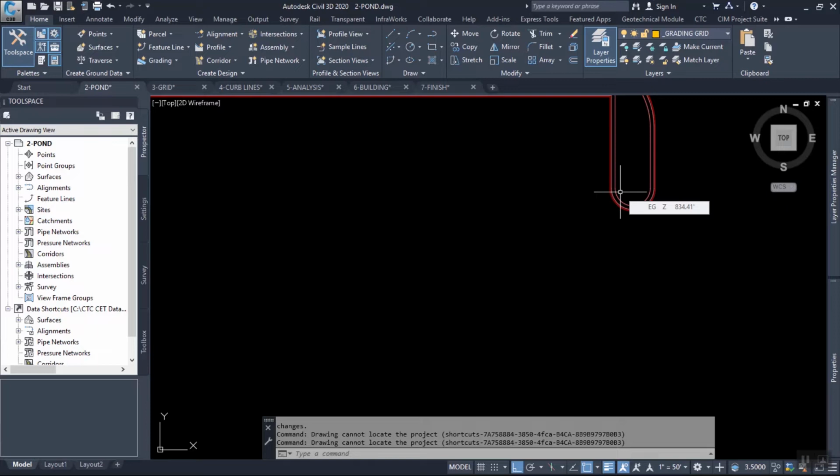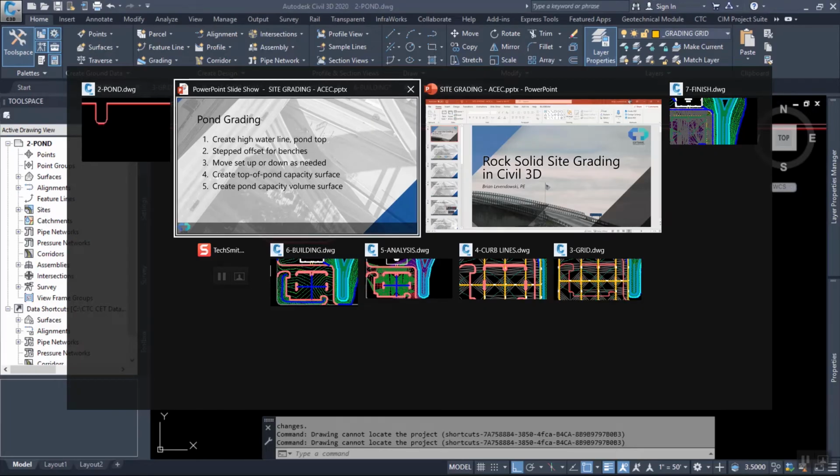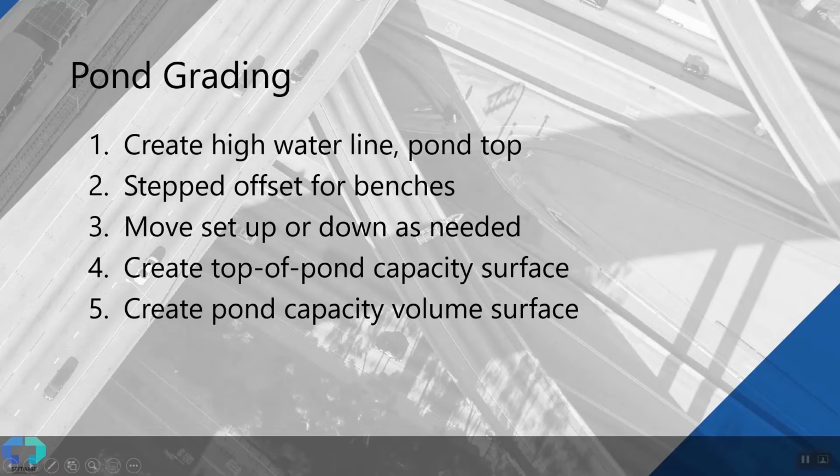Okay, if my whole parking lot sheet drains one way, it's great. So what I'm going to do is show you how to use it, but then at some point you say, well, I can't control enough of it with that. And then we step away from it and we do more detailed grading. But I still think there's a good use for a setup surface to get you to at least 75% design. So those of you who've never seen it, I'm going to walk you through it here. Those of you who have, hopefully I've got a few new tips for you.